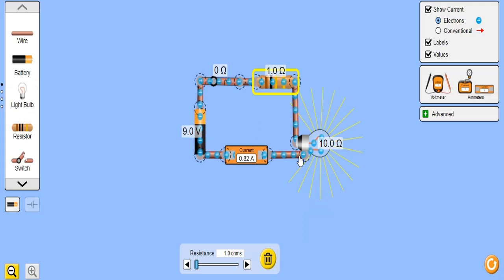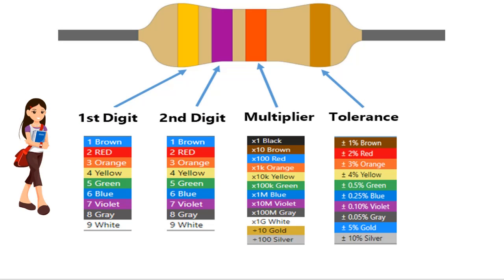With a 1 ohm resistor, the lights are bright, and the electrons move fast. When the resistor value is increased, the light dims, and the ampere decreases. I understand that a resistor is used to limit the flow of electric current. Resistors are round and small, so color codes are used to show the value. Resistor values are usually standard values, first and second digits like 10, 15, 22, 33, 39, 47, 56, 68, 82. And then with the multiplier and tolerance we get the resistor value.